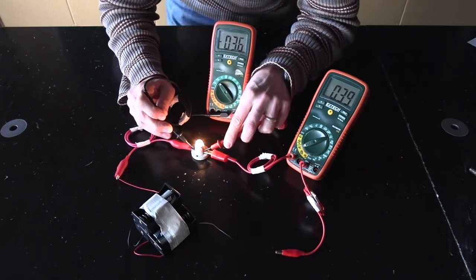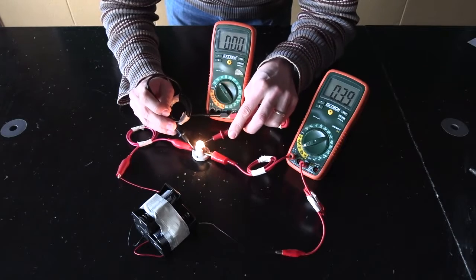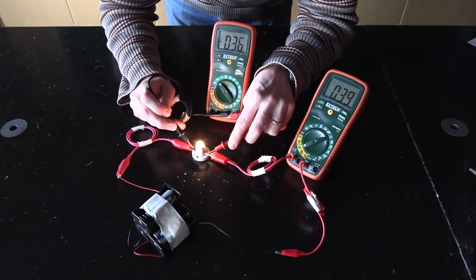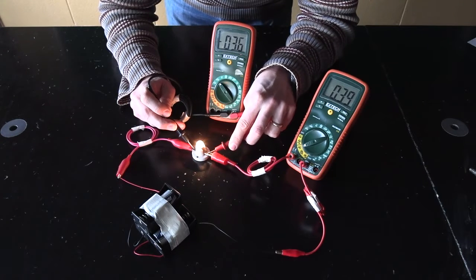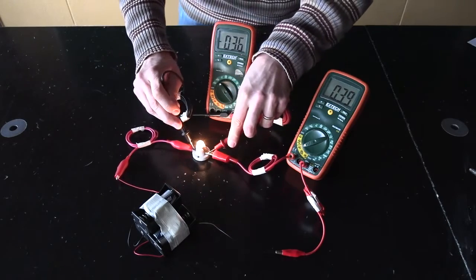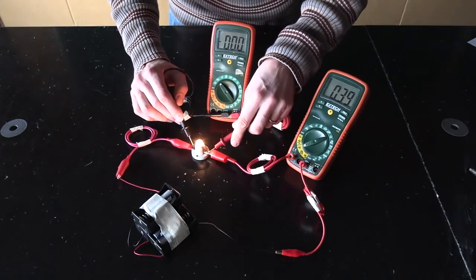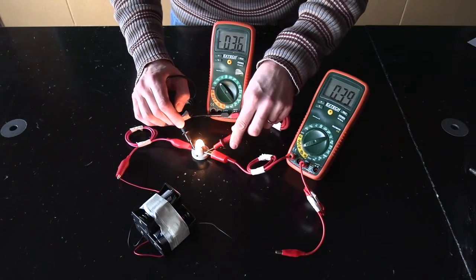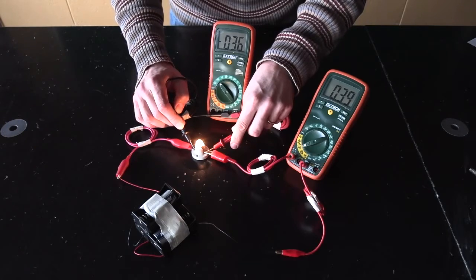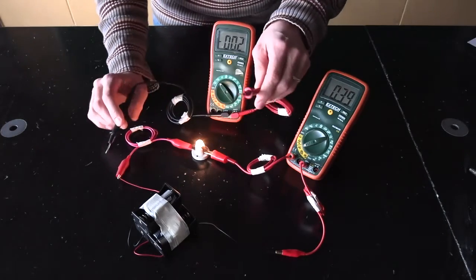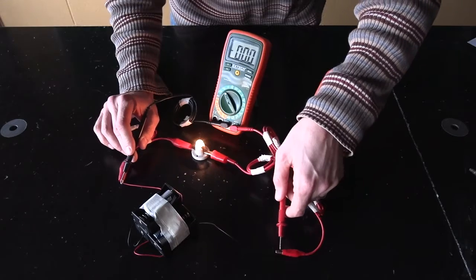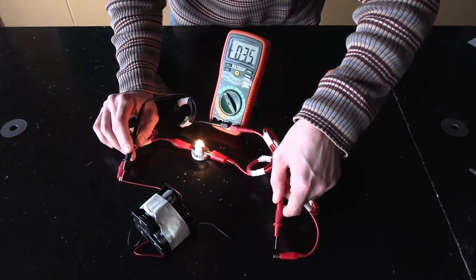So notice now that since it's from one side of the bulb to the other, it is actually connected in parallel to the light bulb. Right? So it's not in series. It's not within the original chain. It's like off to the side in parallel with the bulb. And that's how you use the voltmeter. Okay? If I wanted the voltage of the batteries, I could go here in parallel to the batteries.